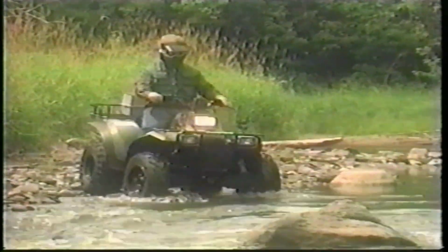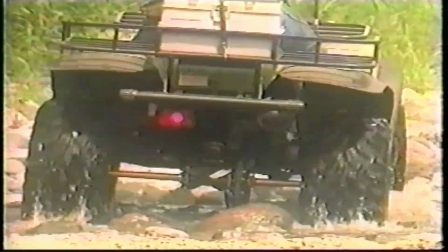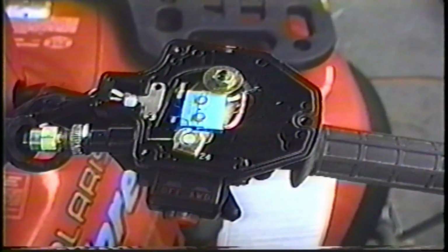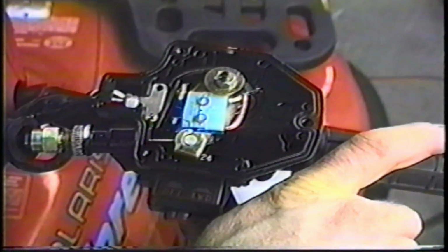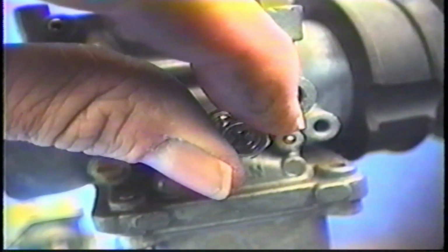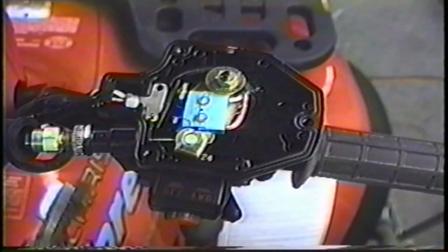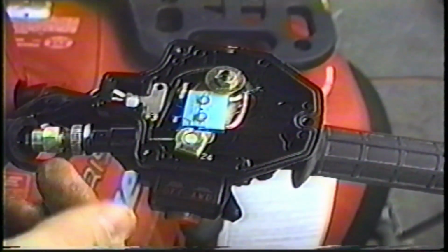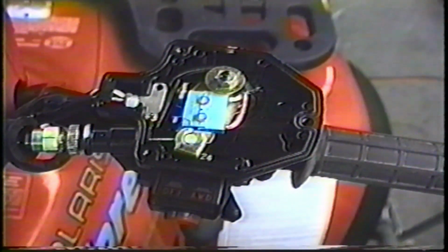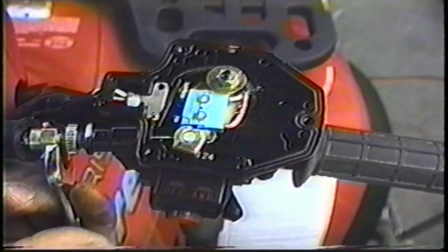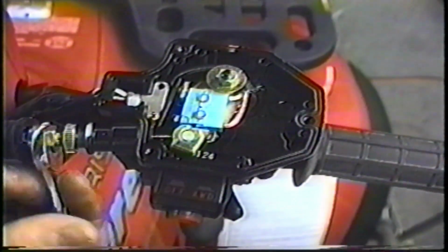On Polaris ATVs, an intermittent spark or occasional engine backfire can be caused by an ETC switch that is out of adjustment or contaminated with moisture. The adjustment of the ETC switch is controlled by the throttle lever free play. The procedure is the same for both ETC switch types. Adjust idle speed to specifications with the carburetor idle screw. Loosen the lock nut on the throttle cable and the throttle block. Turn the throttle cable adjuster bolt until the ETC switch plunger is pushed in completely, and the throttle lever has at least 1/16 of an inch free play.